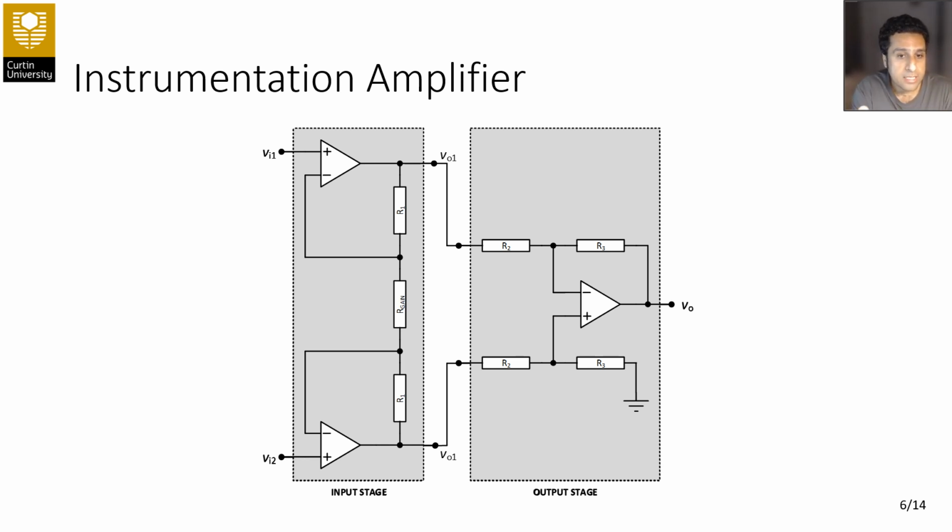So basically, this is a layout that we have for an instrumentational amplifier. It has 3 amplifiers and some resistors. All of these components are usually inside the package, except for this R gain, which is a tunable resistor. It's outside the device. This arrangement has a lot of interesting features, including high resiliency against common mode noises, because it has a very nice symmetry, and a lot of other things that unfortunately we don't have enough time to go through all of them. But let's analyze this configuration with the rules that we just have gone through.